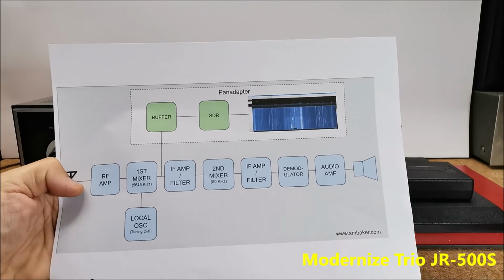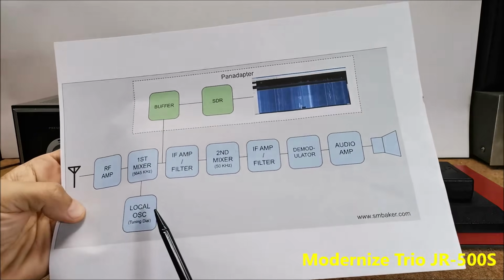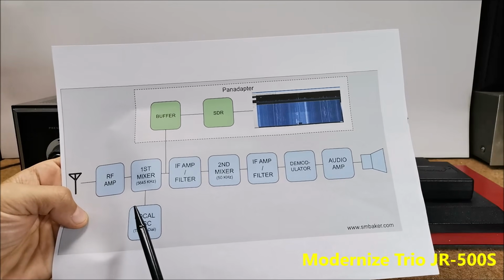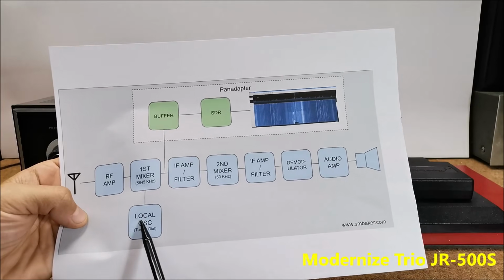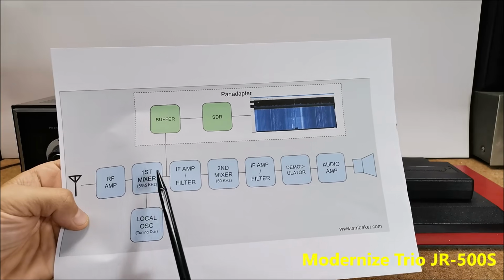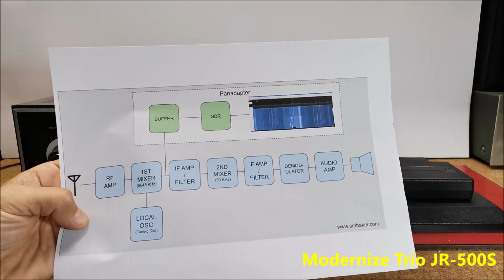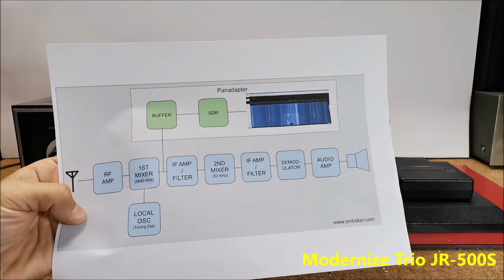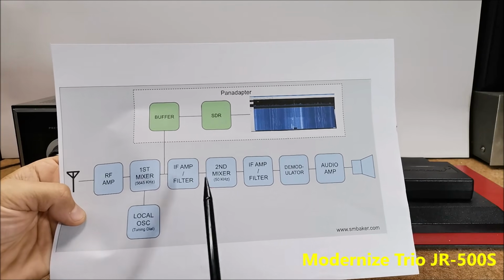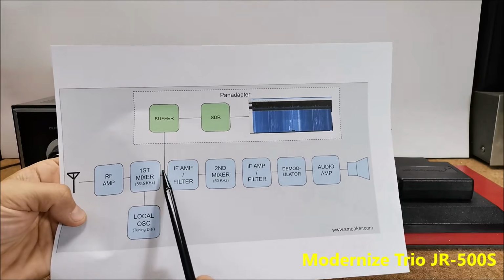Most old tube and transistor receivers are of the superheterodyne type. The incoming RF signal mixes with the desired frequency from a local oscillator to center that frequency around an intermediate frequency. In our case, this intermediate frequency is 8.9 to 9.5 MHz. So we should place the buffer amplifier immediately after the first mixer as shown in the diagram. So here.